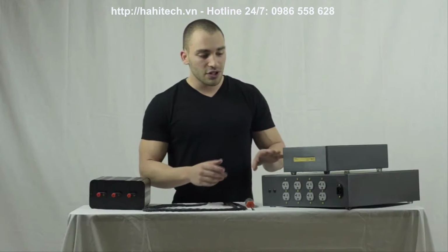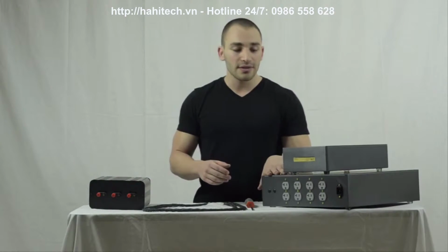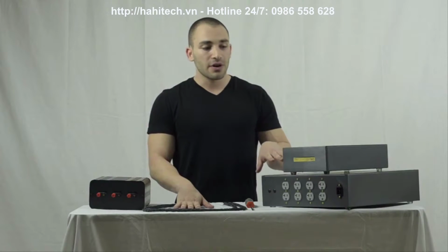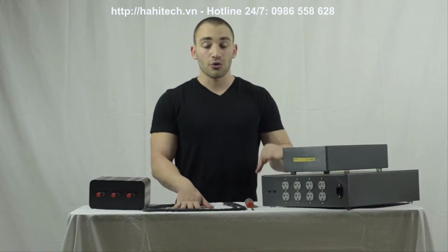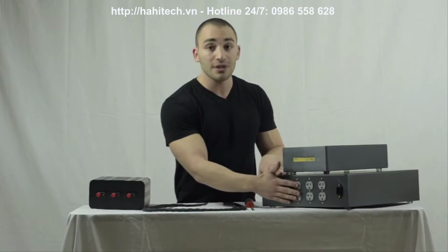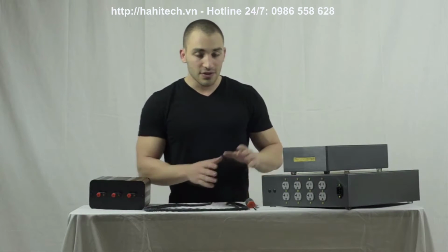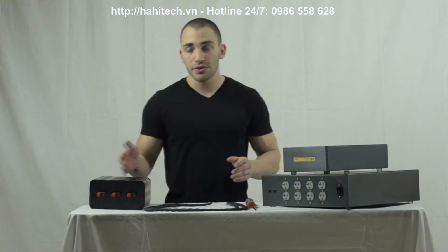So like I said, the first thing you want to do is ground your system to one receptacle, to one point. If you're using a power distribution system, it's very important that the internals of that system are grounded to a single point, so you try to keep the voltage differences between these outlets as close as possible. And this comes into play as an entire system, so you don't want to have half your system grounded into two different power conditioners because they're going to have differences in voltage.